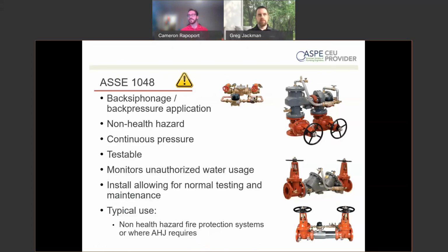And the big thing here is there is a bypass. So it's pretty clear on this, little 2-inch guy up at the top. You're after the first shutoff and before the second shutoff, you are going into that bypass. You're running through a meter. You're going through another backflow preventer, right? Because if you're bypassing a double check, there has to be a double check in the bypass.